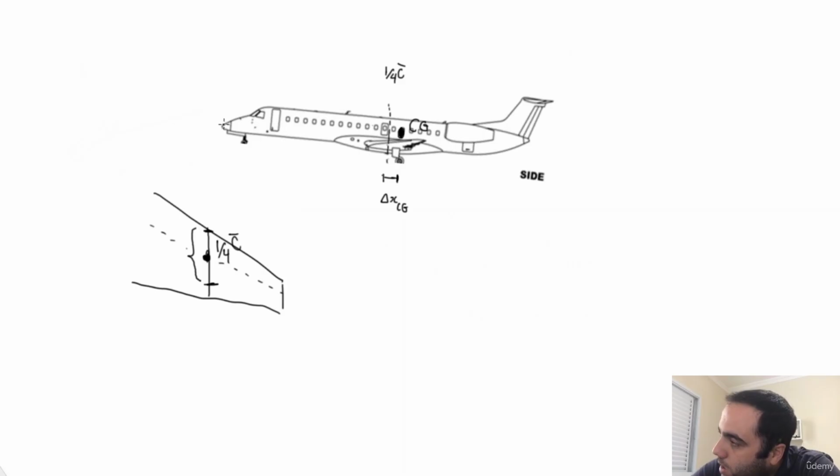So let's say that my reference of the aircraft is right here in the plane of the wing, which normally is. So we have this length here that we call the ZCG position, the position of CG. And we follow the same convention that we have: it's a negative ZCG if it's up from the origin. So let's say the origin is here, so 25% and the wing plane. So here we have a negative ZCG, and if it's below we have a positive ZCG.